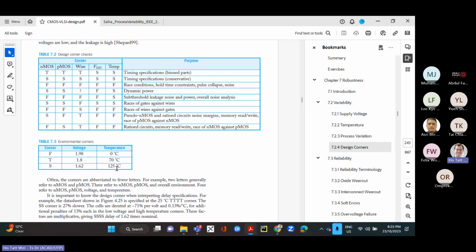Well, because as you change this temperature and operate at the fast corner and the slow corner, sometimes if you're not careful and the design is not robust enough, you will break the max delay constraint or the min delay constraint. You might create race conditions in the fast corner. You might have situations where you violate hold time and setup time in the slow corner, meaning the logic is too slow in propagating and you violate those timing constraints. When you have timing violations in a process corner, it means that under these sorts of process variations, your design will fail. So normally you simulate in these process corners to see how robust and how strong your design is, how capable the design still is of meeting the specifications under these different process corners.